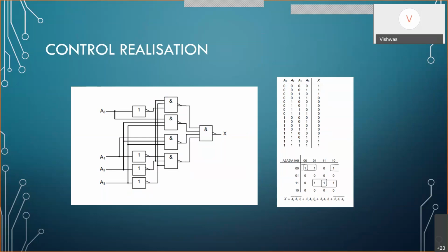Currently, you might have seen in your home washing machines also, there is a word called fuzzy. Fuzzy logic, or fuzzy control, has been implemented here. That fuzzy control basically deals with the amount of water to let in and the RPM of the motor, which should be controlled for the dirt level. It uses multiple sensors to sense the dirt level. It's an optical sensor kind of mechanism which senses the dirt level, and based on that it will change the RPM. If the clothes are too dirty, it will adjust itself accordingly and put in more water and more concentrated detergent.